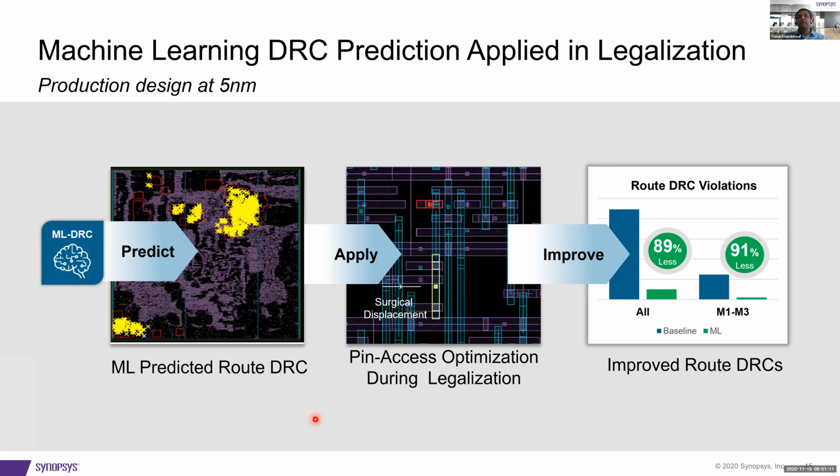So when the placer comes in to alleviate congestion, it's trying to give an easier problem to routing, because there is a very large gray area where the router can always come back and give you a fully routable solution, but it did that after a lot of grinding and adding wire length and adding timing and power, so it doesn't help overall PPA. So really from a placement perspective, what we see is that any model that's predicting only detailed route DRC can only augment the way general congestion is being modeled today. So that's really the direction.